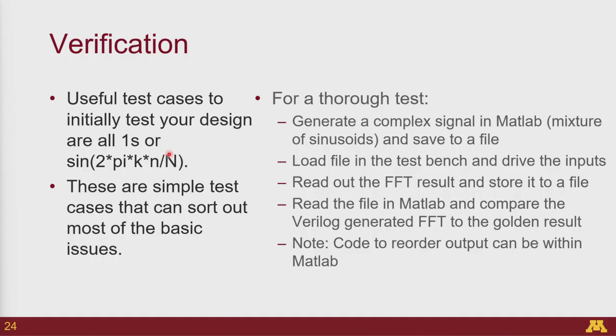Similarly, when you get the output of your FFT block, just take the output and store it directly into a file and then post-process it in easier software like MATLAB or Python. That way you don't need to implement things like a reordering circuit; you can handle all of those within your MATLAB or Python script. So this way you get a more versatile way to check it, and you can also compare the results from your block versus a standard implementation in MATLAB or Python.